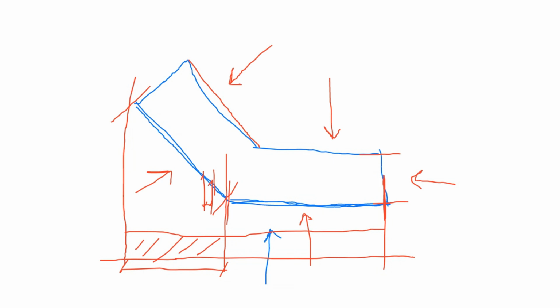And come here, draw another elevation, and come here, draw another elevation, so that everything is projected at 90 degrees. You don't project any inclined surface to the vision that you're seeing, because this is not an actual reflection of your building. So in this case, what you would show is 1, 2, 3, 4, 5, 6 elevations.